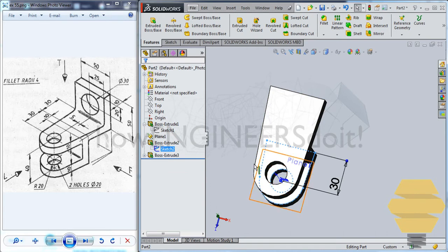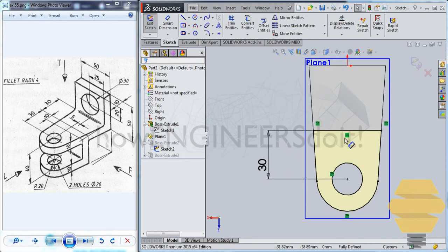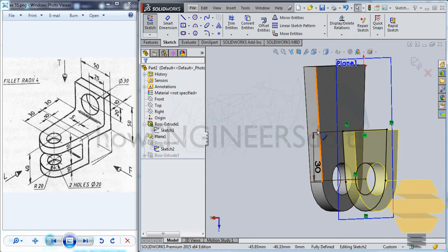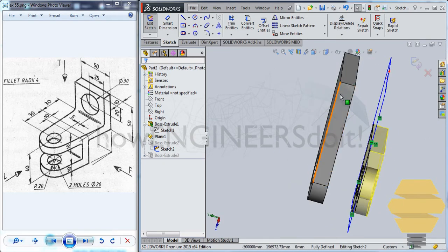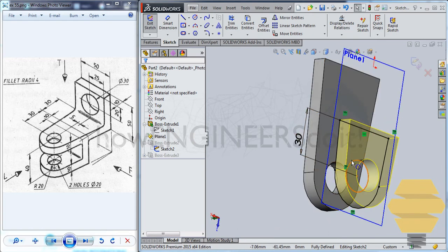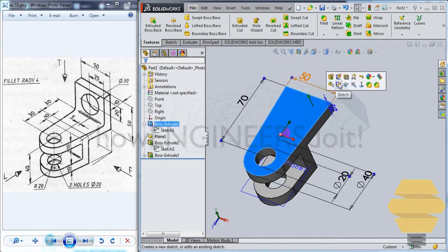If I had selected, for example, I've gone to this sketch here and I'm just doing a normal view. I have taken these lines, this arc, this line, and all those from the previous model here. If I had drawn the line by myself, then if I had changed any parameter over here, the same information wouldn't be transferred to the sketch. So that's a simple logic there. I'll discard the changes. Alright, now we can select this face here and go for the sketch.